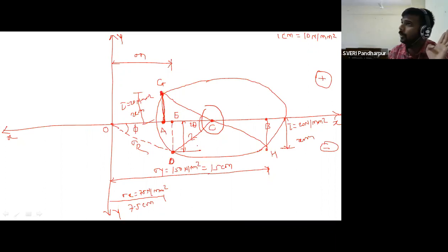So in case number 2 and case number 3, at least you will get the center points, so we can draw the Mohr circles, and by using that we can find out the unknown parameters. So mostly for case number 2 and 3, your graphical method and the Mohr circle method will be applicable. Understood both the procedures? Understood the sign conventions? The sign conventions of the shear stress in the analytical method and in the graphical method are different.